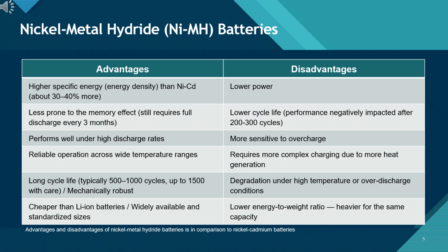However, they have some trade-offs: lower power output, shorter cycle life compared to NiCd, and higher sensitivity to overcharging and heat generation. In short, NiMH strikes a balance between performance and safety, but requires careful charging control to maintain reliability.